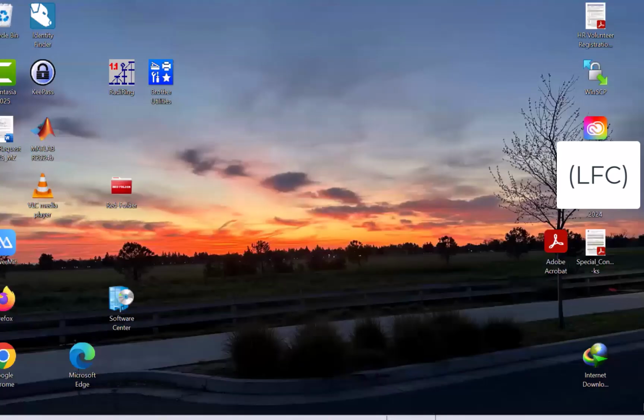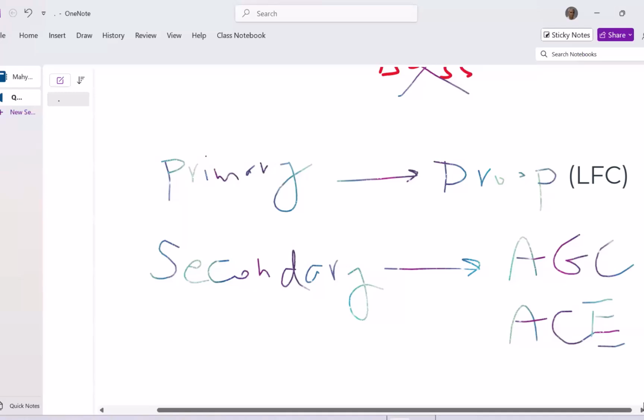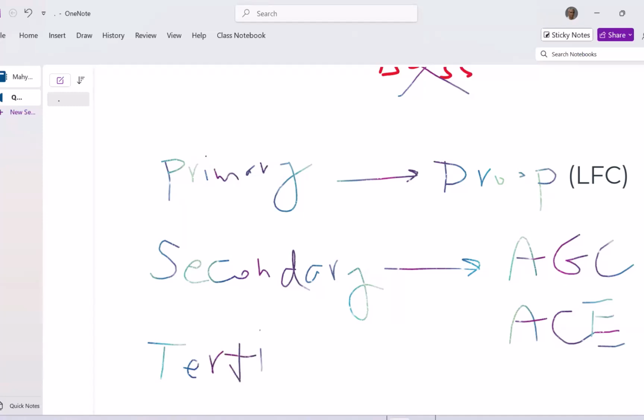Now, in the end, we want to have an optimal generation in our systems, which means that the settings for the generators can happen between this hour and the other hour. So that happens within a few minutes, to an hour, to a few hours in the future. Those settings in the generators have to change based on what we call a tertiary control.